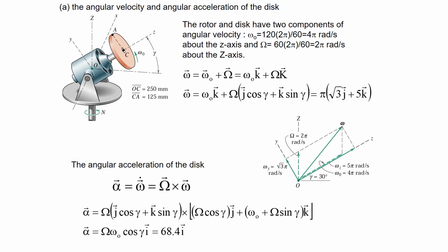So we can put the time derivative as this one. Otherwise, we would also have to include the change in the angular velocity. So that would have been necessary. But since we don't have any change in the magnitude of this small omega spin, we'll simply have this as big omega cross small omega. So that is the cross product.